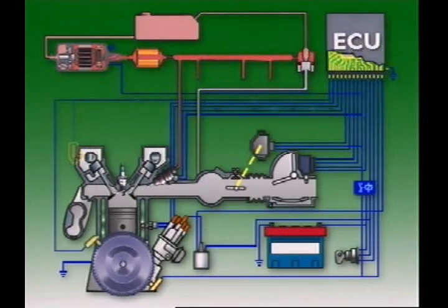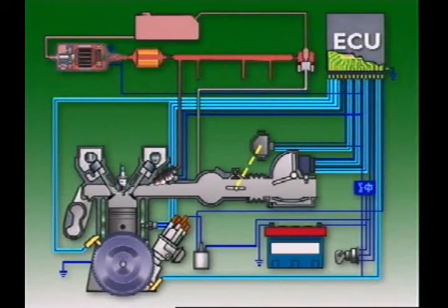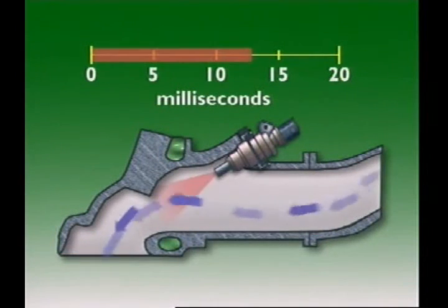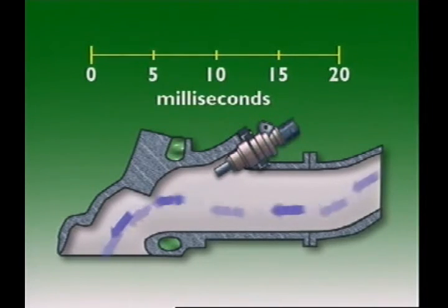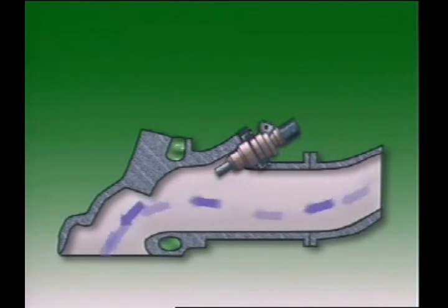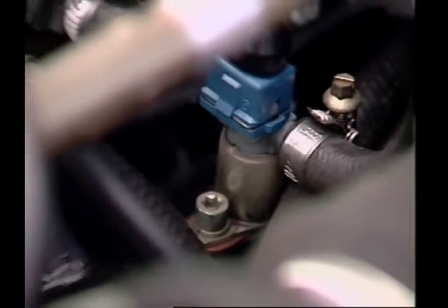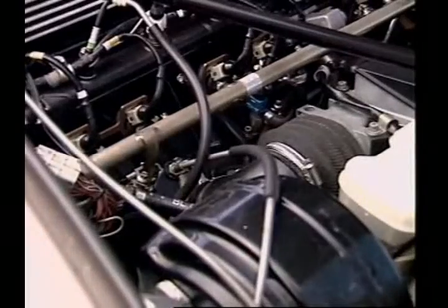Engine fuel requirements change according to engine speed, load, and temperature, so the ECU needs information on these changes. Sensors measure these variables, then relay the information to the ECU in the form of electrical signals. The ECU then calculates the duration of pulses necessary to provide the fuel required. Extra fuel required during cold starting can be supplied by increasing the number of injection pulses, or by fitting a separate cold start injector that operates independently of the main injectors when the engine is cranking.